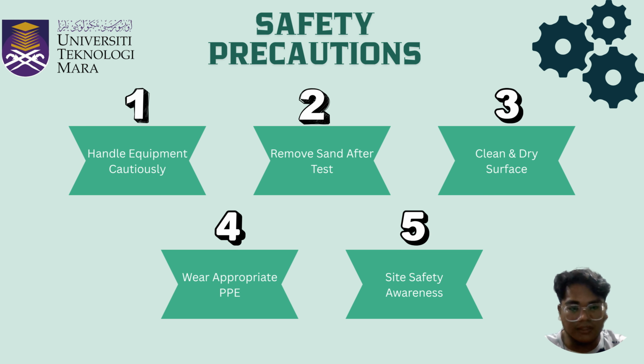First, please handle the equipment cautiously. Next, please remove sand before and after the test. Third, we have to clean and dry the surface before and after conducting the test. Fourth, please wear appropriate PPE, which is a reflector vest and safety boots. Lastly, please be aware of your surroundings while conducting the experiment.